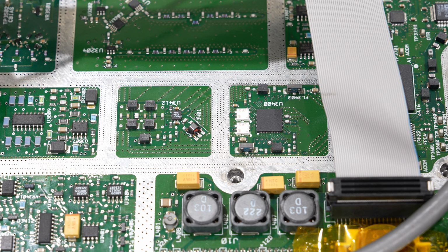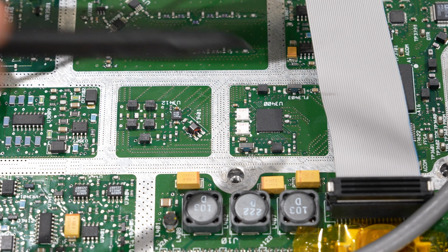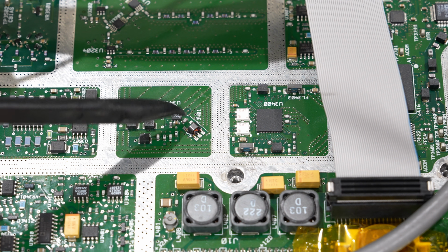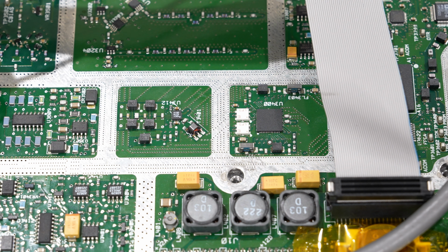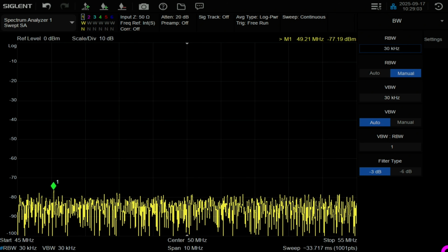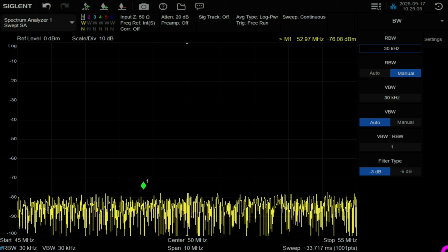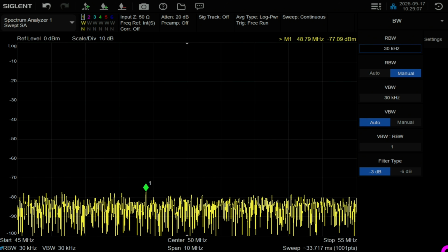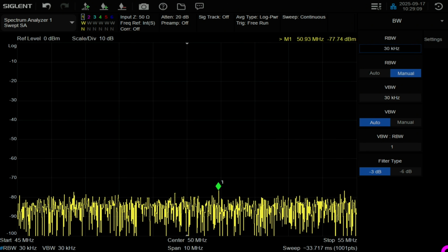So if everything is working and the divider is working and can divide when this is at 1.6, we should be able to see something close to 50 megahertz on both of these things. Let's measure that. Okay, I've adjusted the VCO manually to be around 1.6 gigahertz. The synthesizer is set to ask for 1.6 gigahertz. Let's take a look and see if it makes sense.